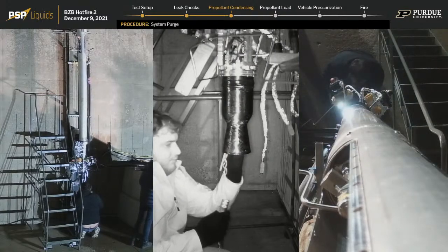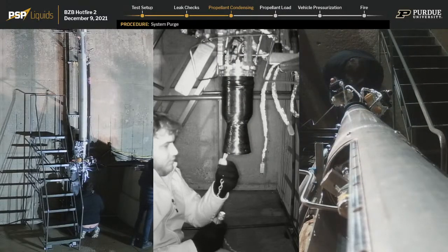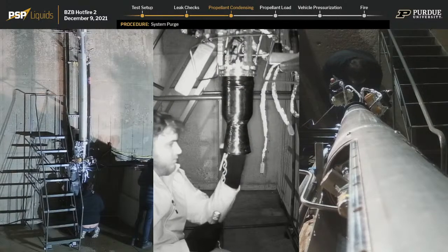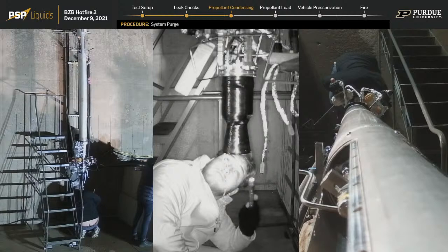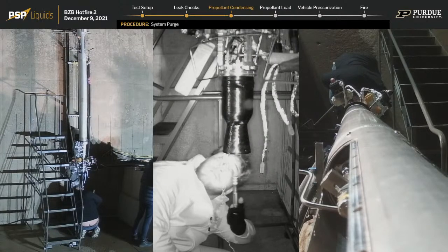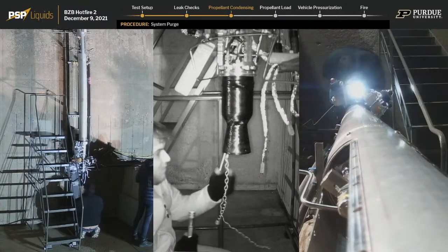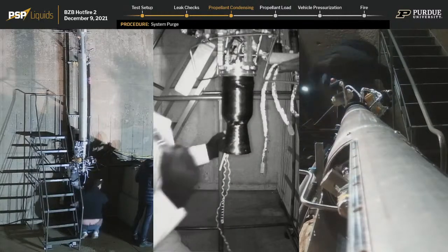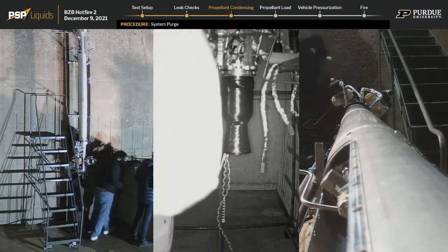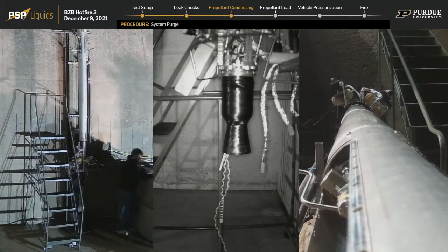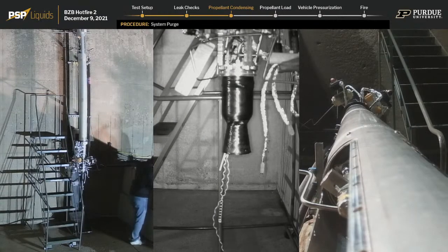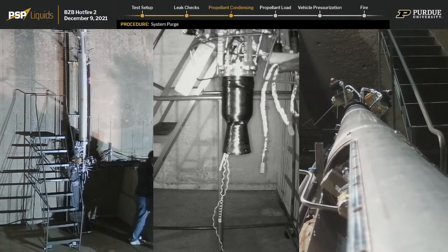Why? Do you know why that was? Yeah, so after our last Hotfire, we determined that having that redundant capability was not necessary. Both of them fired, and so we decided to move, I think, to redundant E-matches instead. Yes. And there was actually a risk presented by having redundant igniters. By having both of them in there, one of the igniters actually swung out upon ignition and ignited methane in the lower fin can bay.